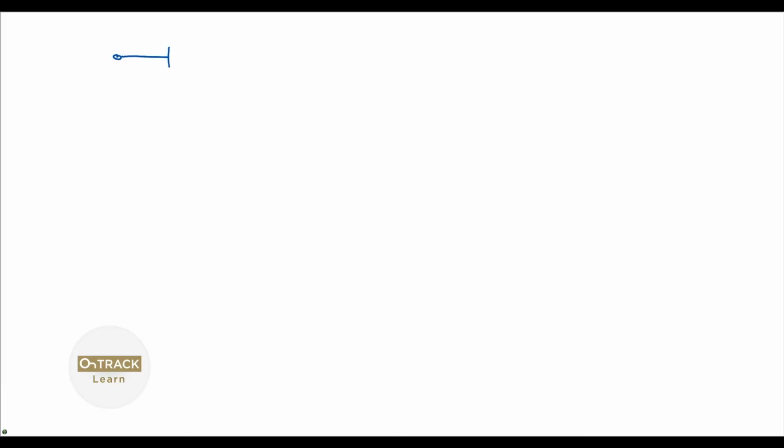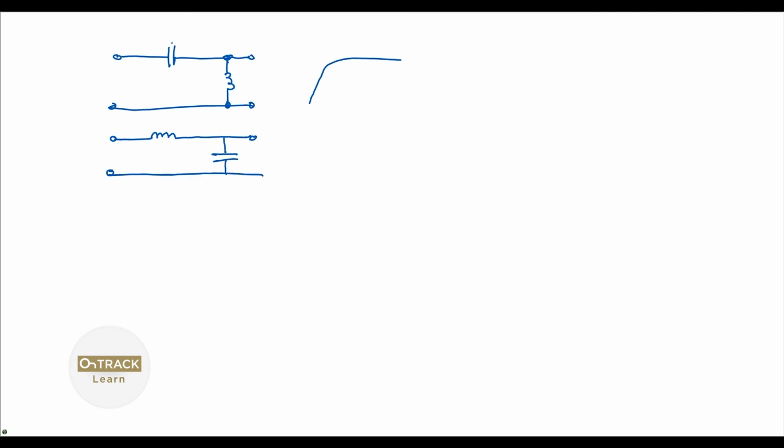Now, of course, you can also introduce more capacitance in series if you want a high-pass filter. And so how would you do that? Think of a capacitor as being two plates again. You have two conductors near each other, with a lot of E-field coupling between them. That's a natural high-pass element. And of course, if you have some parallel inductance or shunt inductance to ground, that's your typical high-pass filter. And of course, we have series inductance, like a normal transmission line trace with shunt capacitance.